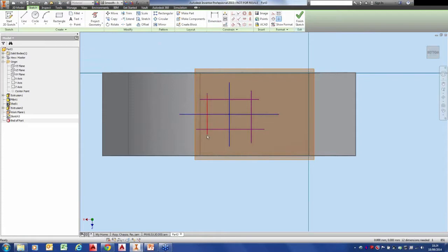I'm then going to apply a few constraints, not too many, just to roughly position where I want the ribs to be. So from there to there, I'll say it's 100mm. From there to the top of that line there, I'll say is 220. And there, I'll say that's 150. So these are going to be the rib positions. Obviously I could put a lot more in, but I'm just doing a few for this example.